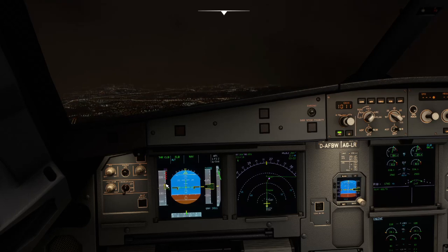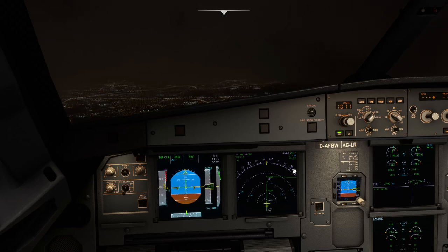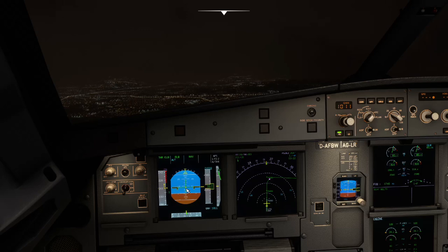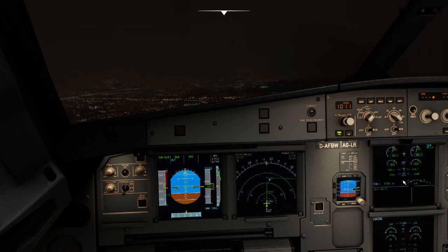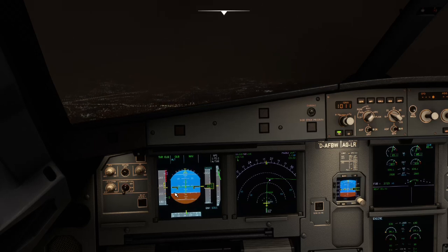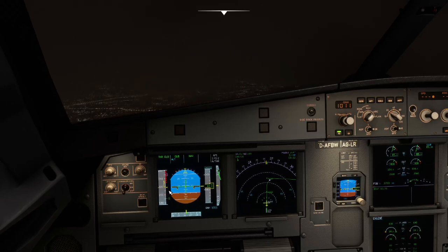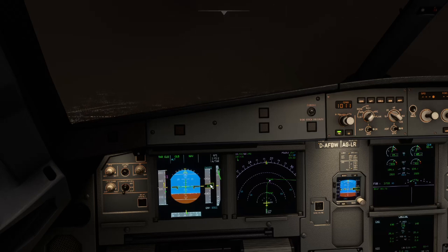Here are the flap limits, obviously, for the next flap stage. So flap 2 limit 200 knots. The first stage of flap will auto retract, and the slats you'll have to pull up manually. So there goes the flap retract. Green dot, which is the min clean speed, is going to be up around 220, so I'm just delaying the slats, moving the slats now. You can see the green dot there is about 215.